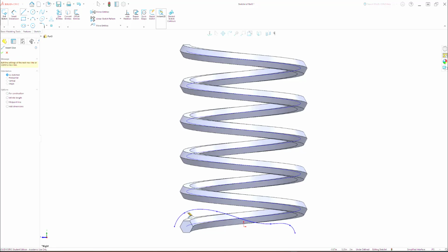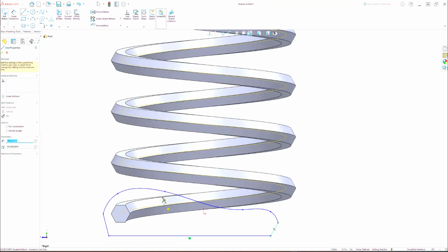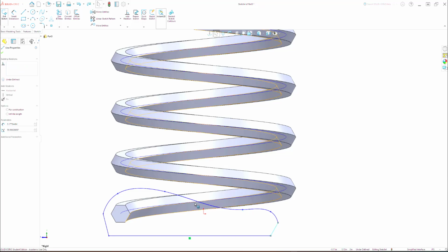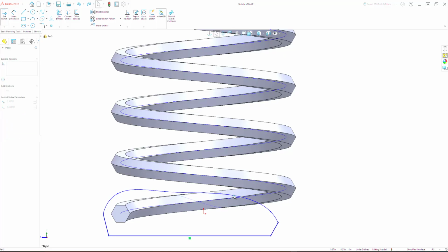We'll add a couple of additional lines so it completes the shape, one linearly across the bottom, and then connect to that data point. Now the advantage is that we can grab these spline points and adjust them. So the way that this looks and feels and shape, it was still in the line mode. So I need to undo that last step. Boom, there we go. And get out of the line properties. Now we can take and adjust the spline. And that's the advantage of using a spline, is that we can take these points.